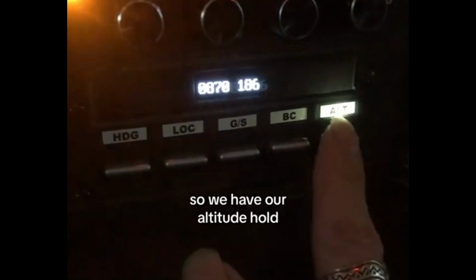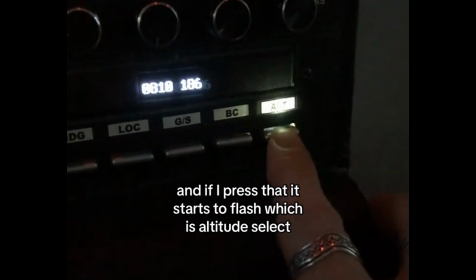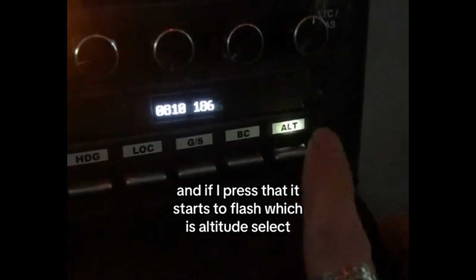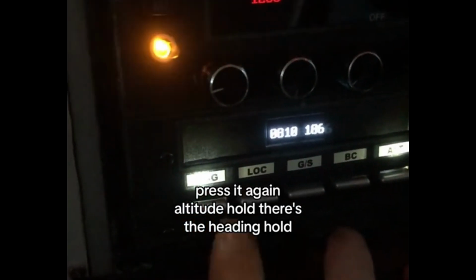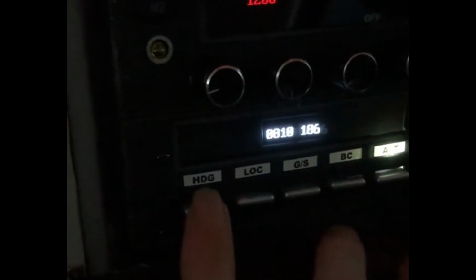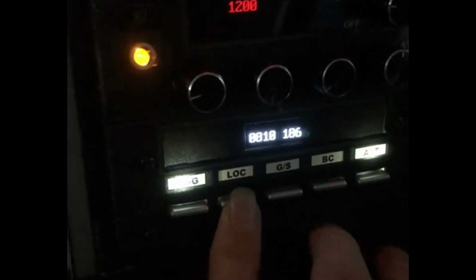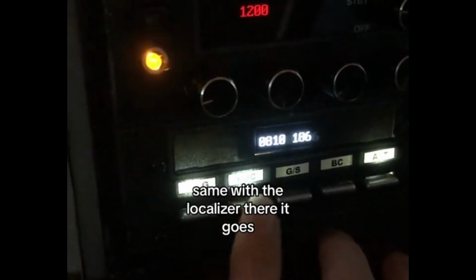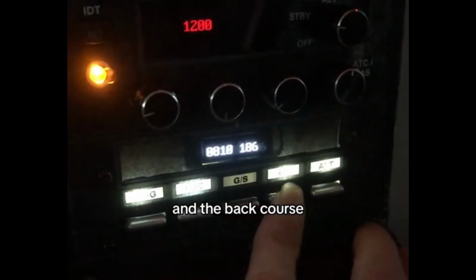Let's check out the autopilot controls here. So we have our altitude hold, and if I press that, it starts to flash, which is the altitude select. Press it again, altitude hold. There's the heading hold. I'm having to press that a couple of times to get it to work. Same with the localizer. There it goes. And the back course.